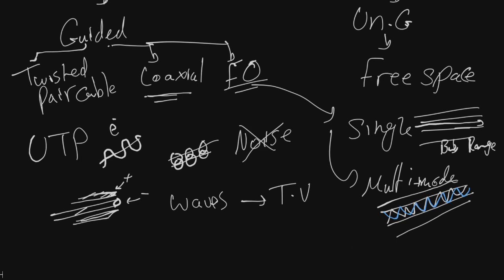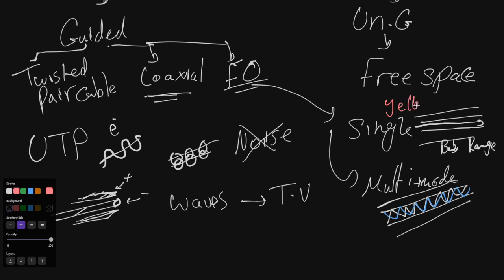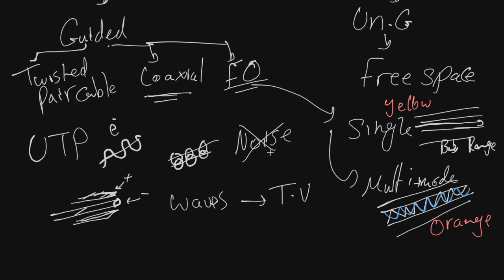How can we find out whether our cable is single mode or multi-mode? Single mode is usually yellow, and multi-mode is usually orange. If engineers are installing optical fibers around your house, it will be an orange color, because this is usually the multi-mode. This is not the one you use for long range transmissions or high speed transmissions. It's more for multiple fast transmissions using optical fibers.